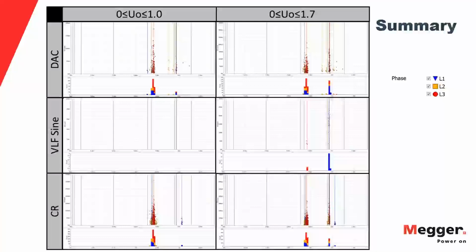So I was being serious, but being a little bit joking about it. You can't call up the system operator and ask them to raise the voltage for you for your online PD testing. So how do you determine the inception voltage? Assuming that PD is not present already at operating voltage, how do you raise the voltage up to determine what your inception voltage is? You can't. It can't be done, because to raise the voltage up for your test cable, you'd have to raise the voltage for the entire system.